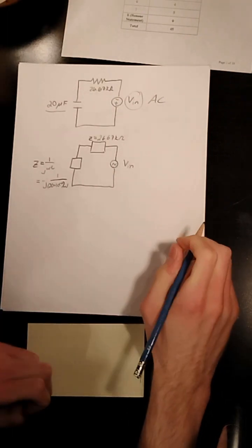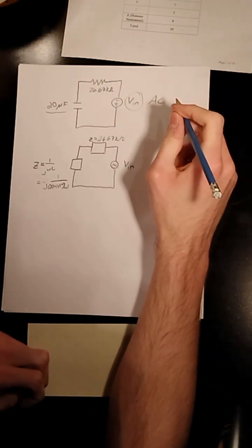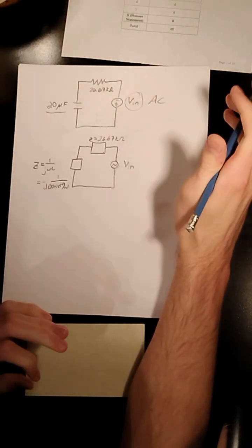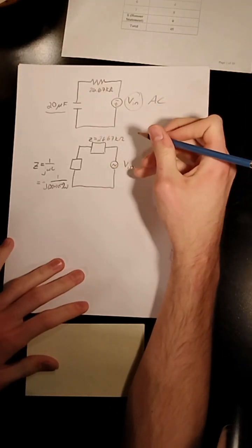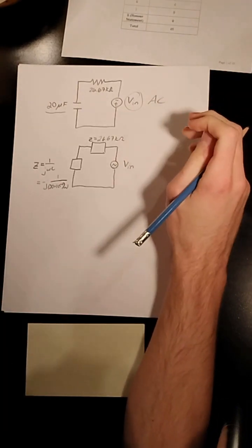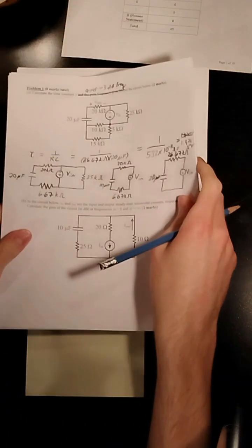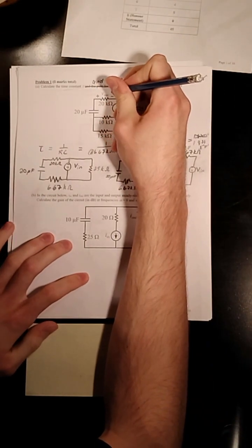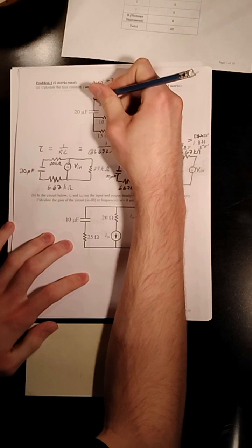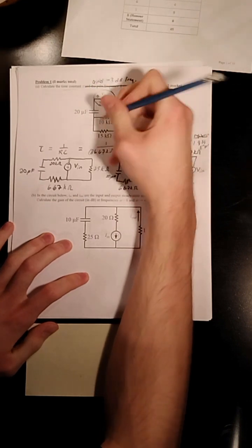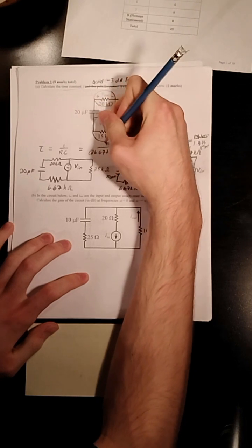So the question becomes, at the 3 dB frequency, when is V out, and I will bring you back to the original circuit here. V out was only the voltage drop across the 20 kilo ohm resistor here, not the 6.67 kilo ohm that we've got connected here.